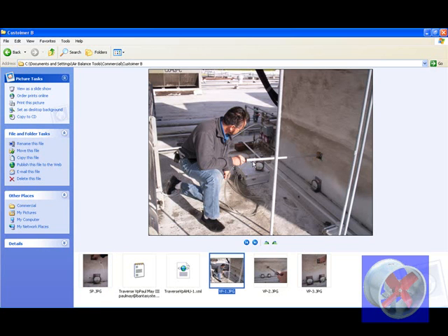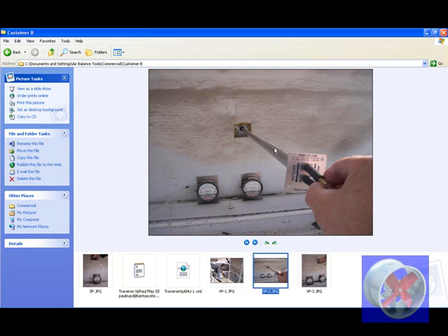So we have a pickup tube tied to a magnehelic gauge that's 0 to 0.25. We expect the velocity pressure coming across the duct to be approximately about 0.15. As we put the pickup tube into the duct, it's directional. Air is flowing down. This is our high side, and it's marked high. And then this is our low side, and it's marked low.